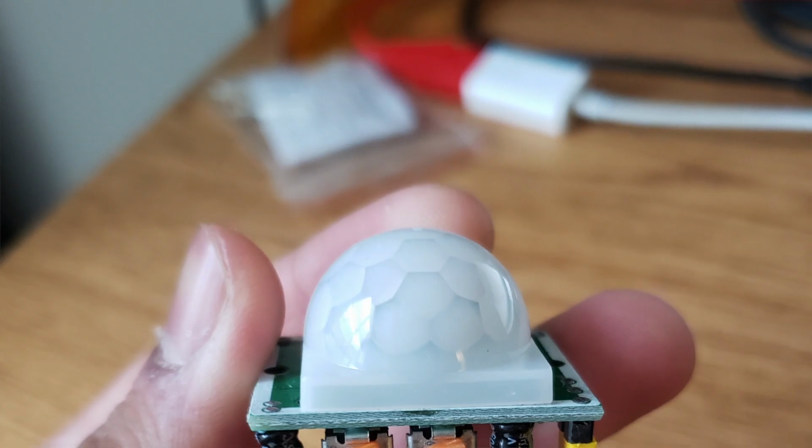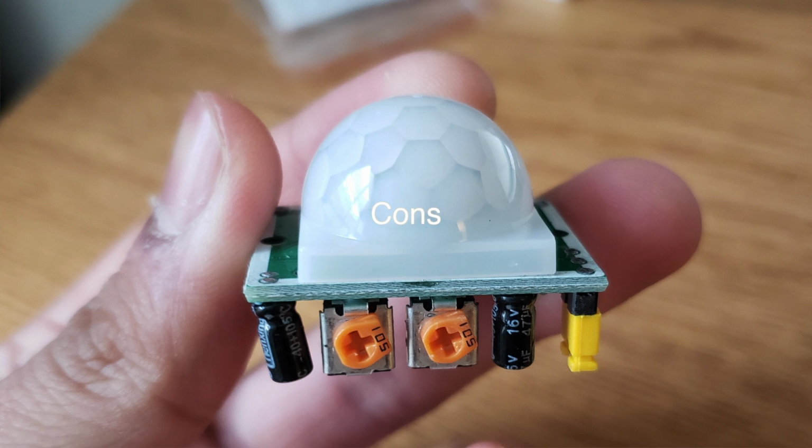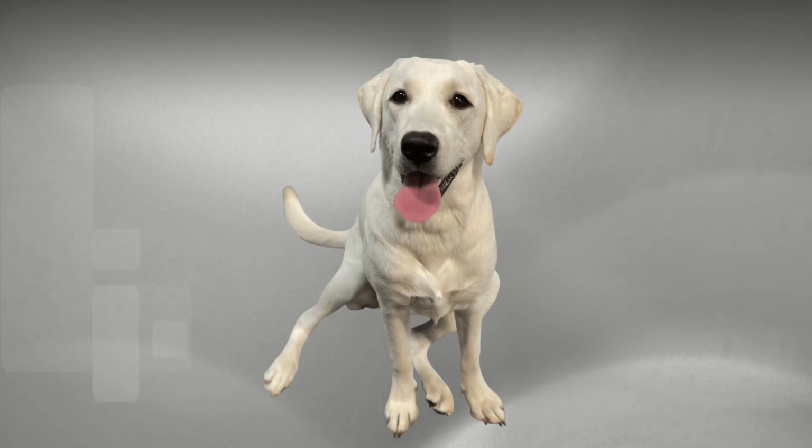These motion sensors are great for security purposes because they base their motion detection on heat, and security primarily cares about detecting life forms, and it is proven to be a reliable motion detection choice in the industry. And like the ultrasonic detector, the infrared sensor was a very easy setup. However, this motion sensor is quite basic. All it really does is detect that something is there. And similar to the ultrasonic detector as well, it is quite susceptible to false alarms, such as non-human life forms.